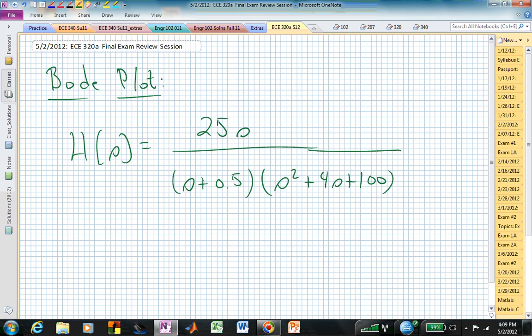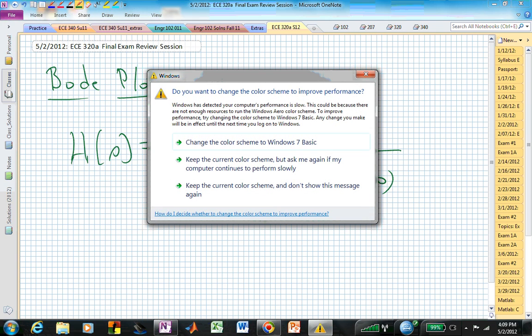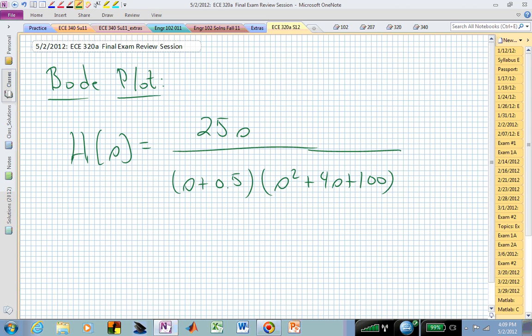And what I would like for you to be doing is learning a way to check your work as you go or even before you go. You can do that by looking at what will or should happen as you're sketching this particular Bode plot. When you have a pole or zero at the origin, that gives you a clue as to what might be happening at low frequencies. In this case, you know where your phase is going to begin at low frequencies, and where is that going to be?